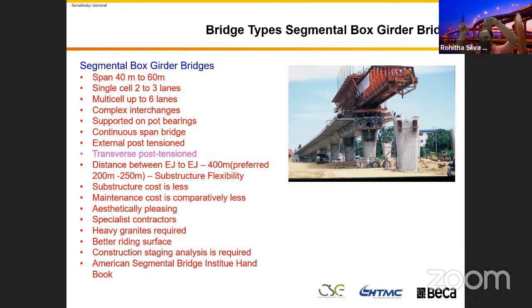So when you apply the point load P, your bending moment diagram is PL by 4. Coming from the support it is 0, at the location of the load it is PL by 4, then the bending moment is constant all the way through at PL by 4, then goes to 0 at the other end. This is the principle they use when designing post-tension bridges, segmental constructions.